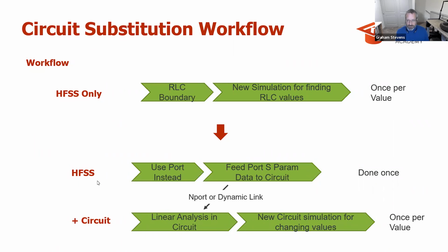And so the HFSS data essentially stays constant. And then as I change the RLC values within circuit, I can get equivalent results to the HFSS only simulations.